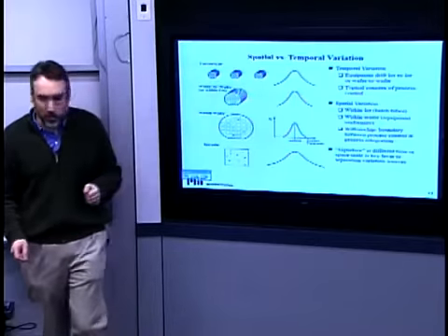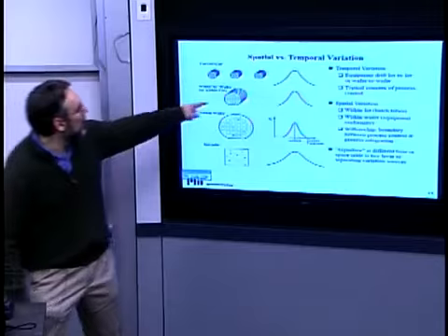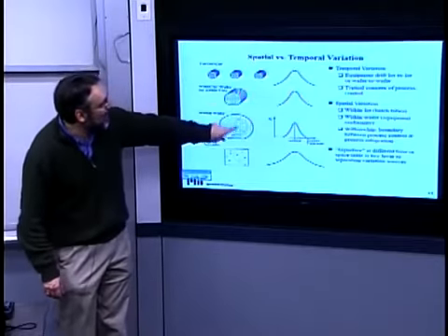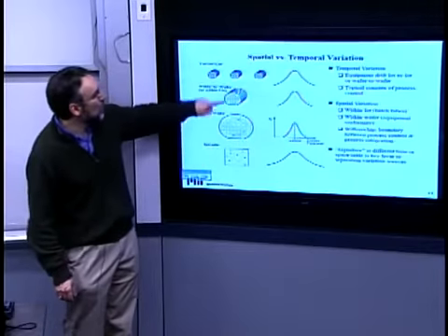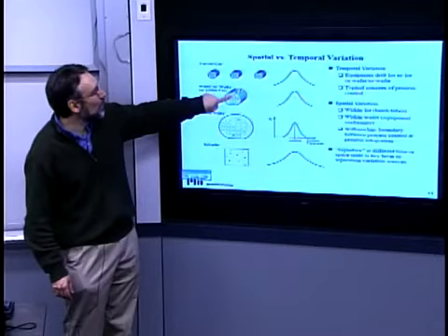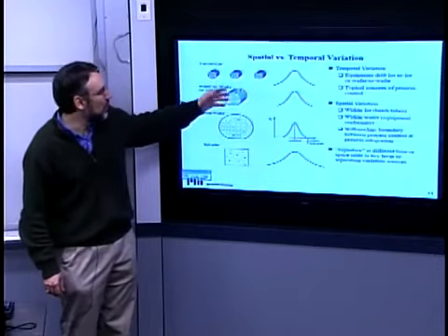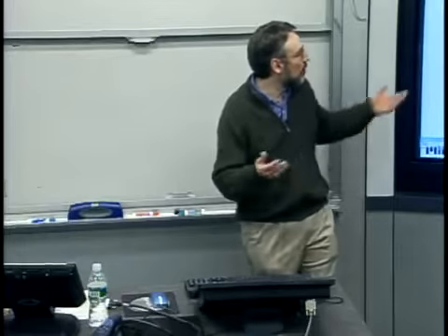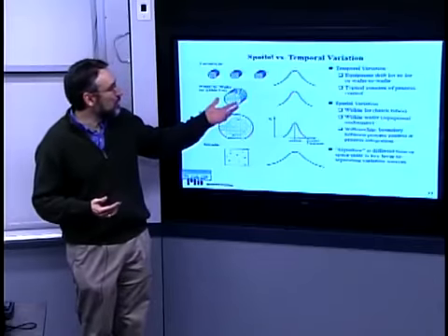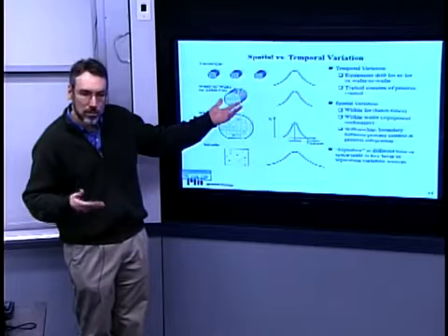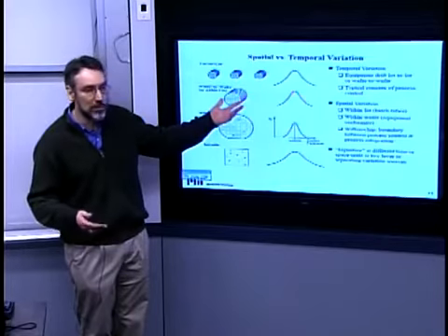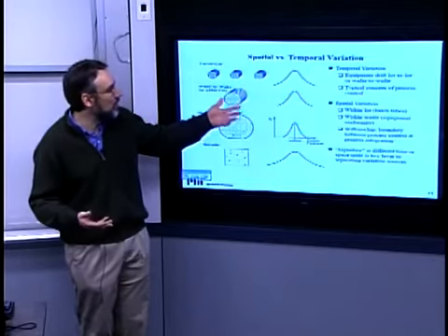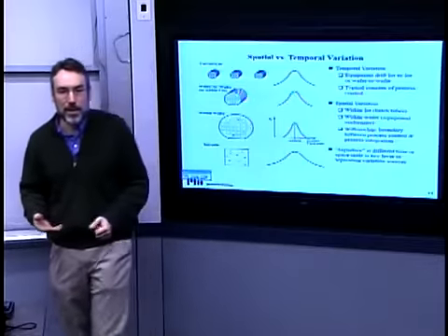And we also can have wafer-to-wafer variations. Again, if I were to either calculate the average over one wafer or maybe just sample exactly the same location on every wafer and stack that up across 20, 24 wafers or large numbers of wafers that might be in one lot, processed even relatively close in time to each other, there's also going to be a deviation.